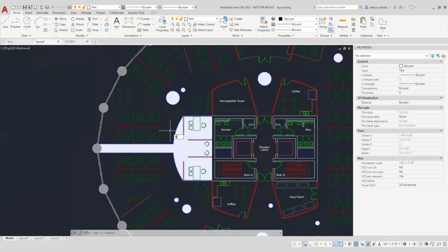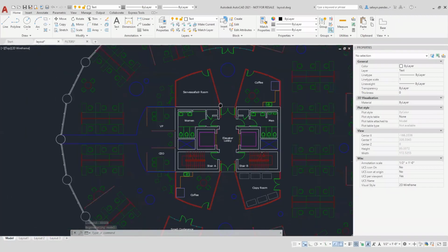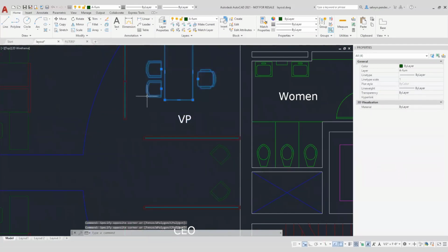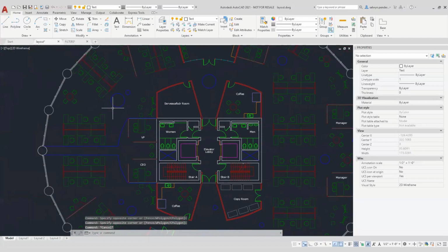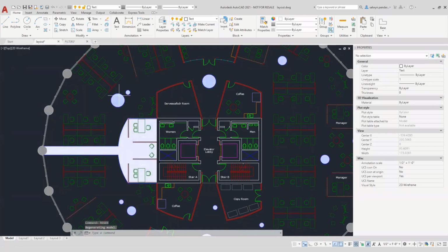There's a command in here called fill. These two commands aren't on the command line, aren't on the menus anywhere, but fill, if it's turned off, we don't see anything immediately, but if we press regen, you'll see that the fill items are now able to be looked through or disappear off screen. So you can do whatever you want in the area where the fill is, any changes or whatever you want. And then when you've finished with the fill, or you want the fill to return, just type fill once more, turn it on, and press regen. And that fill or the fill objects will return to as they were. So it's an easy way of clearing up the screen.